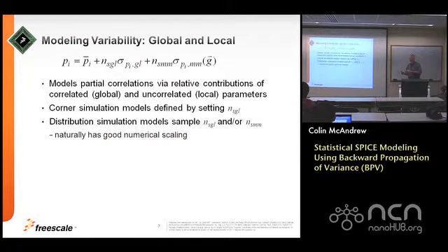And as I've just shown you, the smaller you get, the bigger that variation gets. So this quantity here varies generally reciprocally with the area of the device, or the square root of the area of the device. So the key things here are that we've separated it to a number of sigma times the sigma. If it was a relative contribution, it would be multiplied by 1 plus this quantity, but it's easier to show the absolute variation. And so essentially by partitioning or characterizing separately the amount of local variation and global variation, we can capture the correlation structure between two similar devices. It turns out very easily, that's not what I wanted to do.